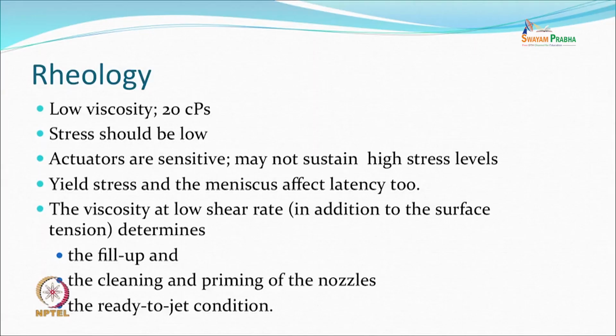Yield stress and the meniscus affect the latency. That means whatever polymer system that we are going to be adding, they will modify the rheology. Viscosity at low shear rates, in addition to the surface tension, they determine the fill up. Fill up means whenever some volume goes out of the chamber, something must come back. Cleaning and priming of nozzles is also important.